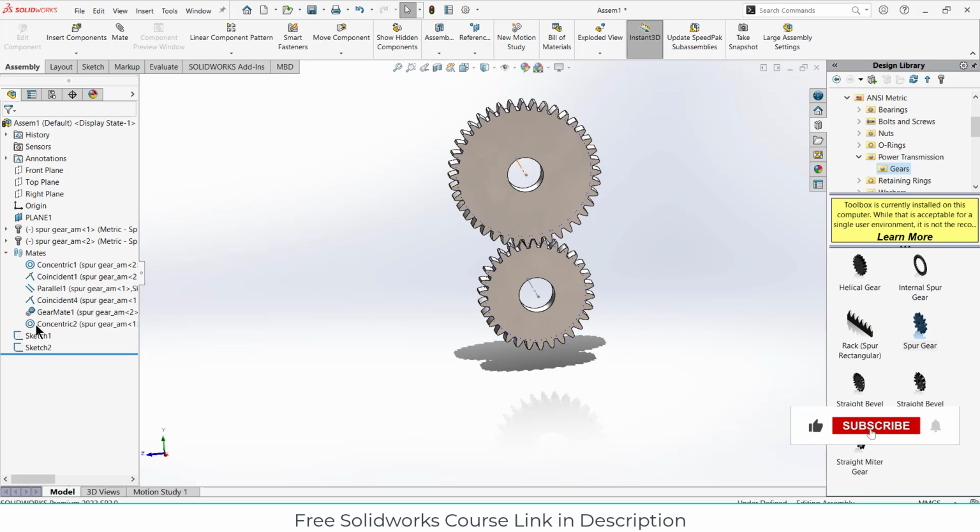Now one thing more you have to do is select this and press F2 and type 40 mm gear distance, so that we know what this sketch is for. Okay, select this power gear because this gear will transmit the power.